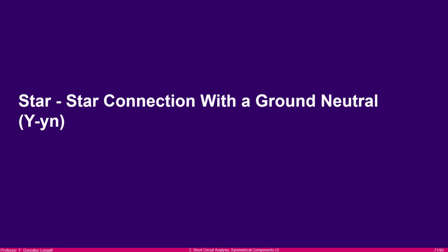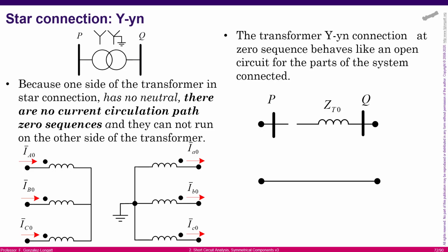But what happens if we have a transformer that is delta connected on the high voltage side, but the star connection is ungrounded, is floating? There is no physical connection between the neutral point on the high voltage side and the grounding point, okay? And on the low voltage side we have a good connection to the grounding point. What I am saying is, in the star connection there is no connection from neutral to ground.